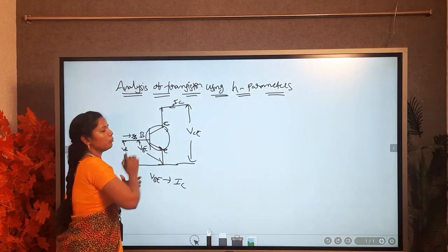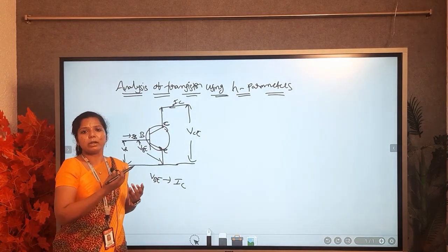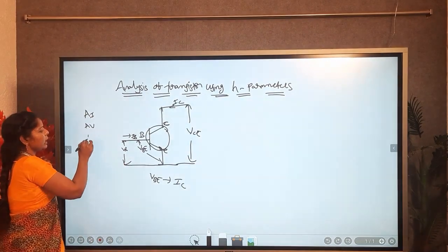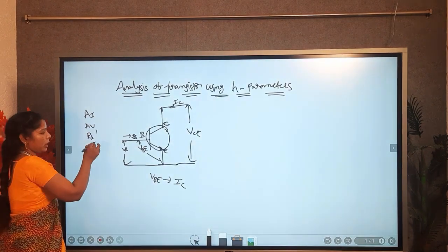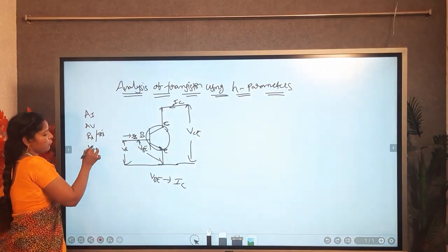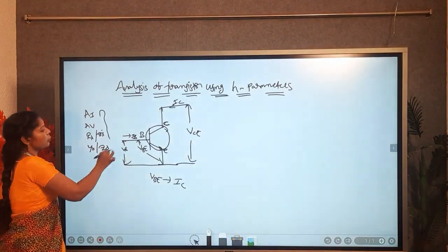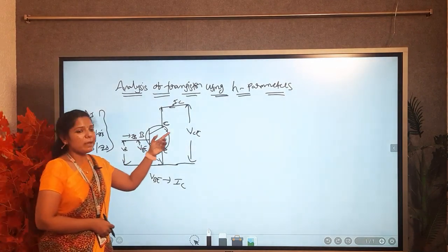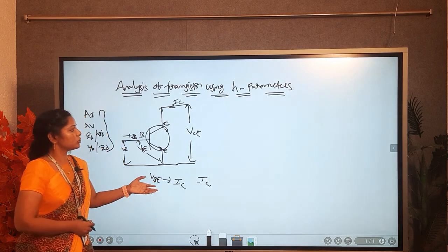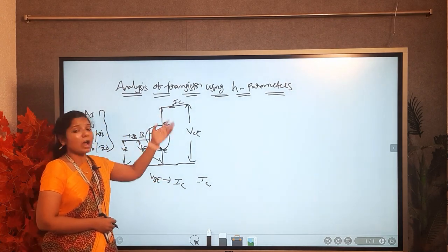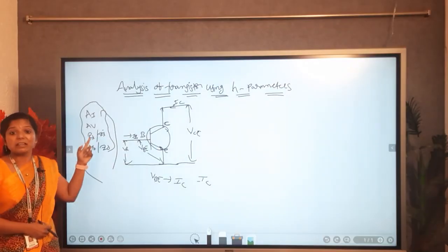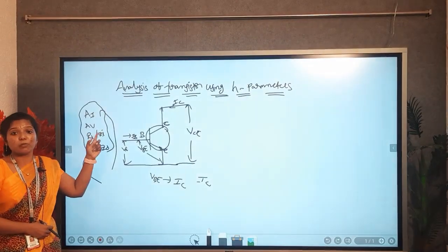Non-linearity in the transistor means that finding any current gain, voltage gain, input impedance (Ri or Zi), or output admittance (Y0 or Z0) is difficult. Why? Because if IC varies continuously, you are not finding these parameters. These parameters are called transistor characteristic curve parameters.